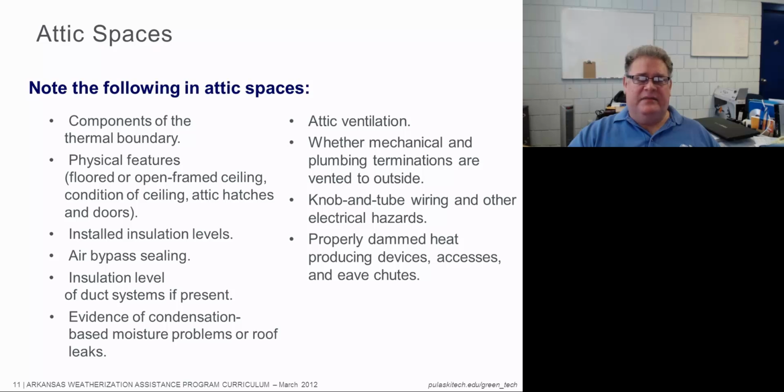Anything that produces heat up there, have we kept our insulation back away from it? And do we have chutes? So chutes and dams. Are we putting chutes into the eaves where we have attic venting to prevent those areas from being covered by insulation, or to prevent the insulation from getting so close to the roof deck? So here's the roof deck.